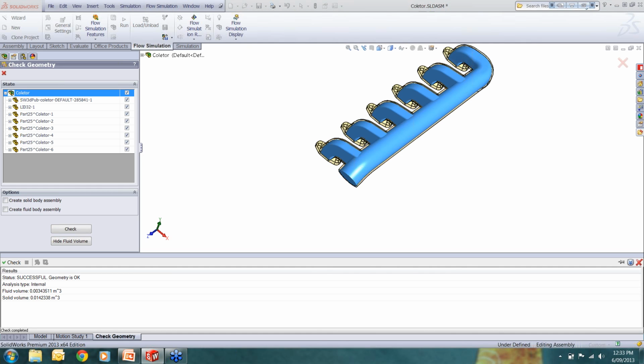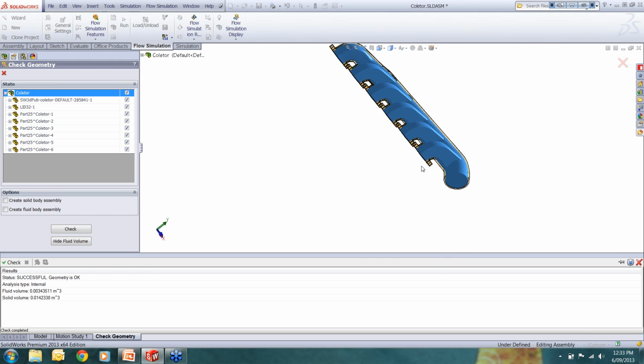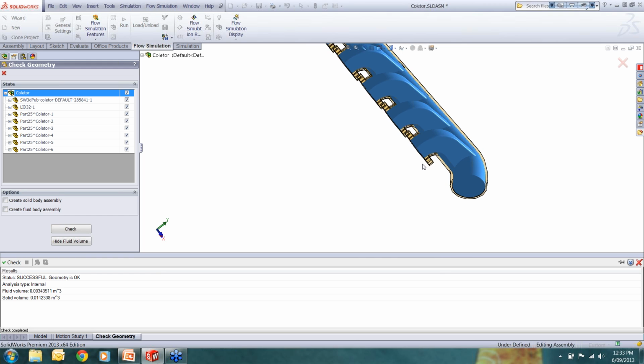Actually, the thickness would matter if it's going to affect your inlet region, so we have to minimize it as much as possible. Usually we think about less than 1% of the entry surface area, and then we will proceed with that. The rest I will show you in the next few steps: we will get the internal face of the lid to apply the boundary condition, and our flow region starts from there.